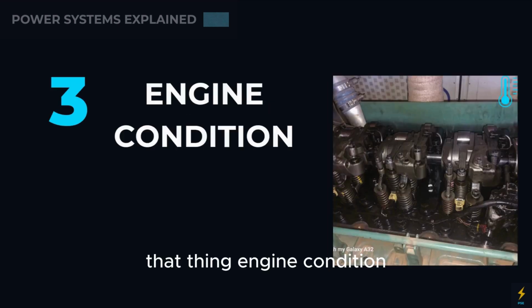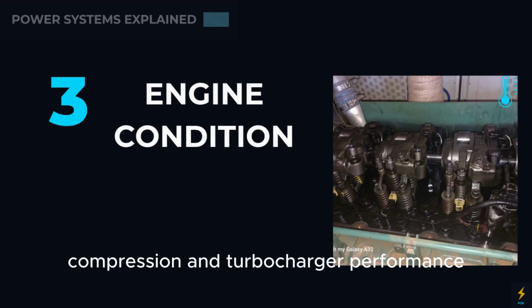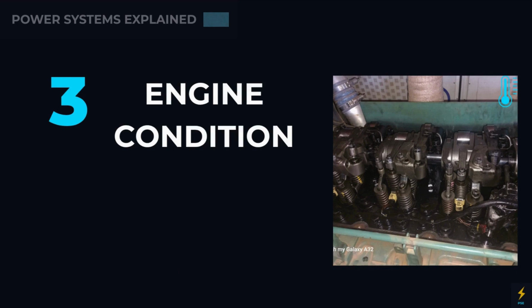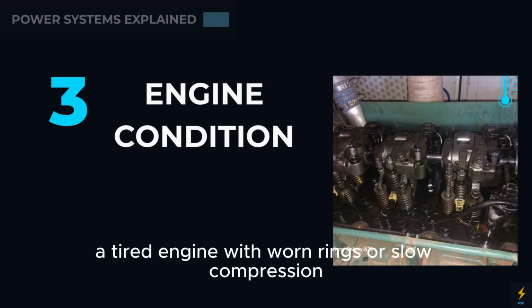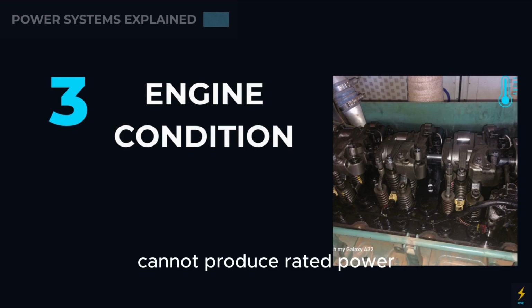Third thing, engine condition. Compression and turbocharger performance. A tired engine with worn rings or slow compression cannot produce rated power. So under full load, it will slow down regardless of governor or fuel.